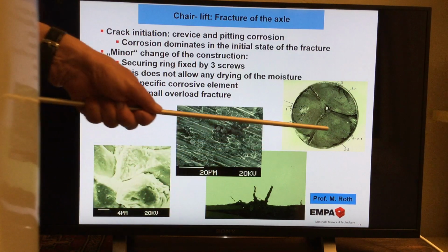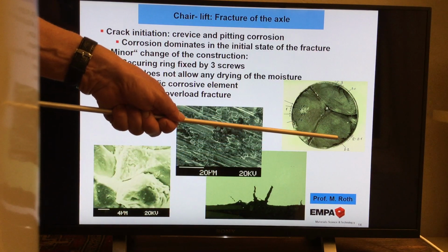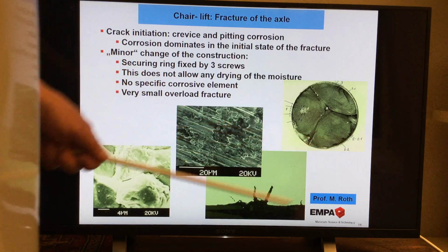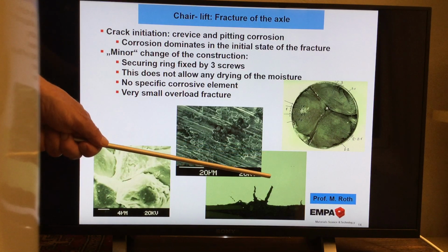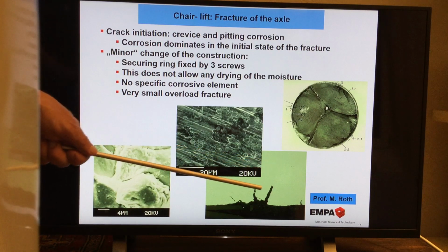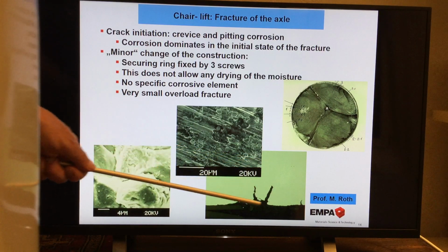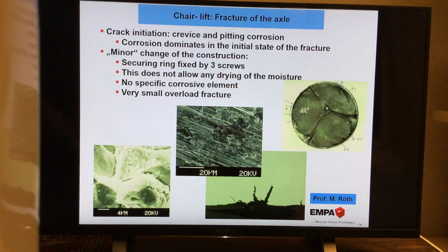However, obviously, due to the mechanism, first slowly corrosion, cracks start to go inside, propagate inside more and more. Then on the crack tip, the stress increases, and additionally we have here a different chemical environment by the time, and this pushes the crack forward.